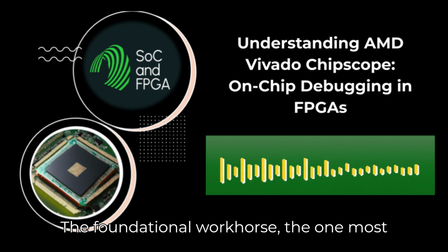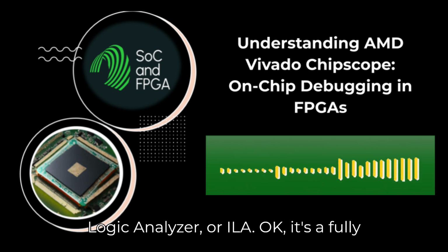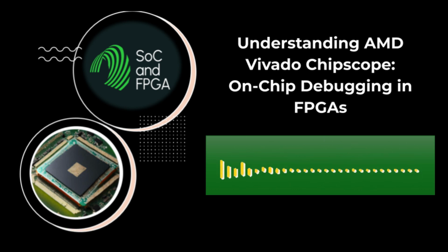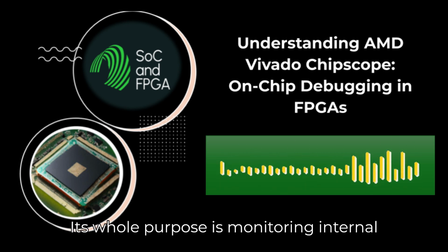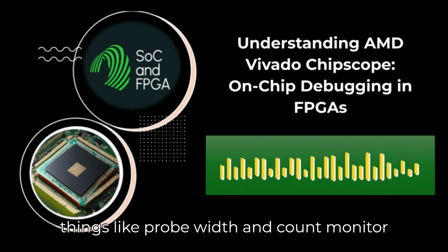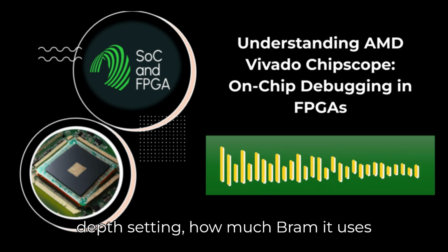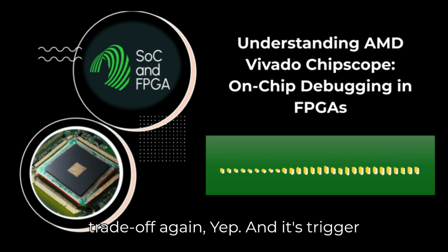The foundational workhorse, the one most people start with, is the Integrated Logic Analyzer, or ILA. It's a fully customizable synchronous logic analyzer synthesized right into the FPGA fabric. Its whole purpose is monitoring internal signals, triggering on events, capturing data at system speeds. You can customize things like probe width and count, monitor hundreds of signals if you need to. Data depth setting, how much BRAM it uses, determines samples per trigger, could be hundreds, could be thousands. Right, that trade-off again.